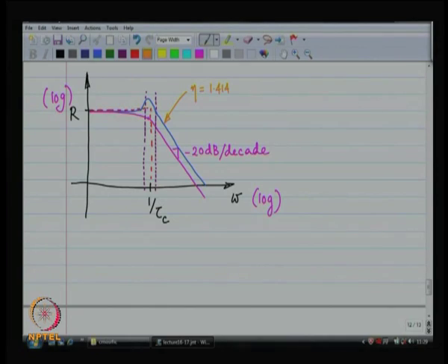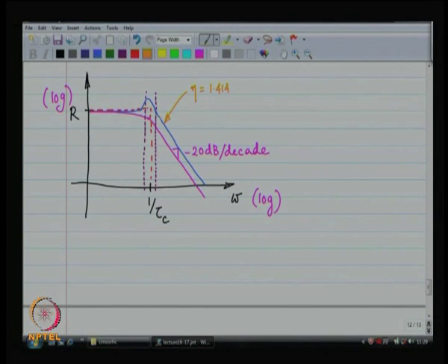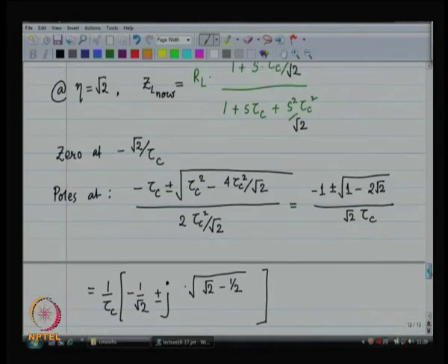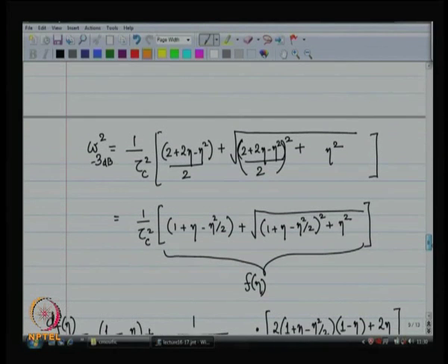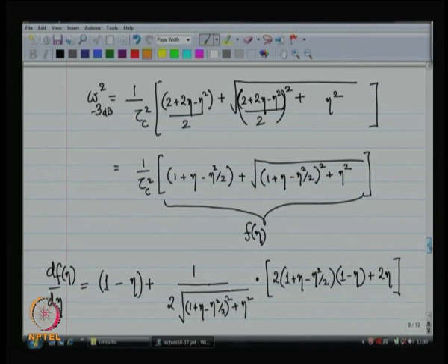I want a flat pass band. So, my 3 dB frequency has increased substantially. I agree, this is probably my new 3 dB frequency, which has dramatically improved. Okay, but I like a flat passband. How much was the 3 dB frequency improvement? We didn't really compute that, did we?